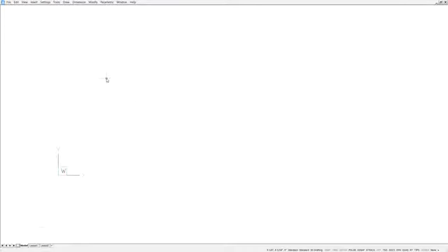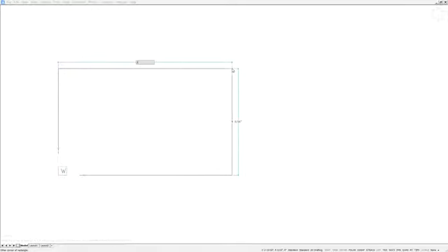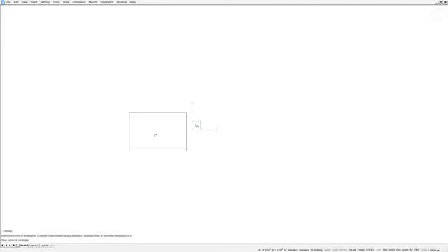So what I'm going to do now, though, is completely use the quad. And I just want to show you how easy it is. You just right-click to access the quad, and BricsCAD is really intelligent, it knows if you don't have any objects selected. So it gives me tools for drawing objects. For example, I can come down here, draw a rectangle, and I'll just pick a point. I'll actually start it at 0, 0, and maybe I want to draw a floor plan. I'll just say maybe 30 feet, tab, just like you're probably used to doing. We'll say, oh, that's a big room, 20 feet. Okay, so you just start drawing.